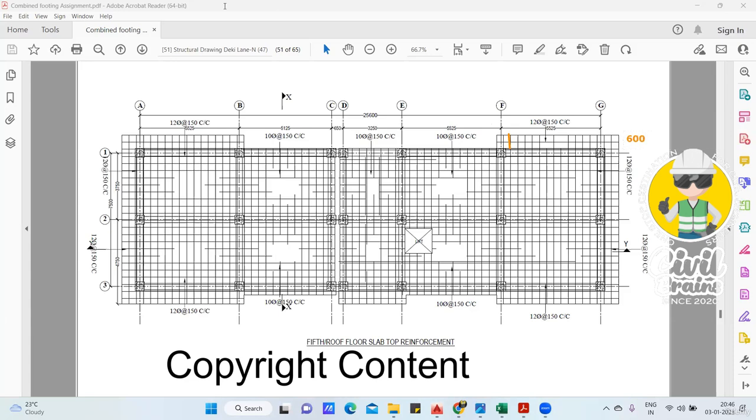Let us say you got a cutting length from here to here, I'm giving a rough example. We got something, let us say 10.5 meter. So in that 10.5 meter, you add this additional portion, because this bar will pass through the beam only. Beam width will be 300, but half was already deducted. So you add 300 plus this, which is 600. So when you find the cutting length, this additional portion you have to add, so that you will do the complete BBS of this. Got it, no? So this is a cantilever portion, nothing else.